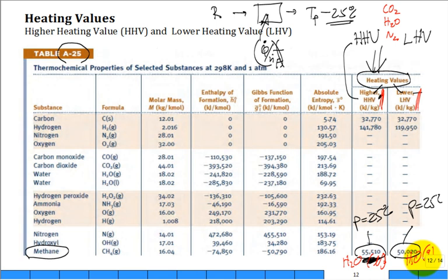You want to get as much bang out of that expensive fuel that you're purchasing. You want as much heat into the house as possible out of that furnace for that fuel that you're burning. Also, the homes get very dry. So no sense sending water vapor out the flue, out the exhaust. So they have things called condensing furnaces. First time you hear that, that doesn't make any sense. You're going to condense inside a furnace? A furnace is hot. What are you doing? Does that resonate? Anybody heard of a condensing furnace? They pay a little extra for that.